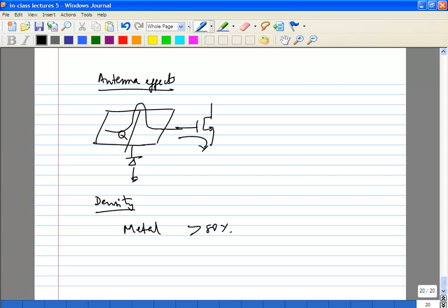So you will have to put in what is called dummy metal. There will just be floating pieces of metal. So your block may be here, and on top of that, they will put in dummy pieces of metal on all metal layers. Okay, it will just be an array, and typically you won't even be able to see your circuit once it's filled. Okay, and now obviously, for sensitive circuits, you want to prevent this.